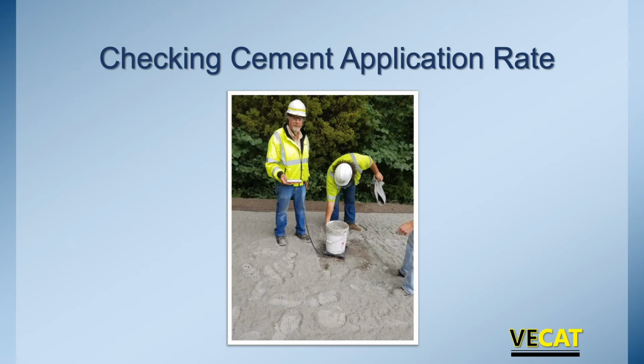And now they put all the cement in the bucket. They knew the weight of the bucket. Here it is sitting on some scales. We're having a digital readout. And now we've checked the application. So again, making sure that we're within 0.2% of the job mix formula.